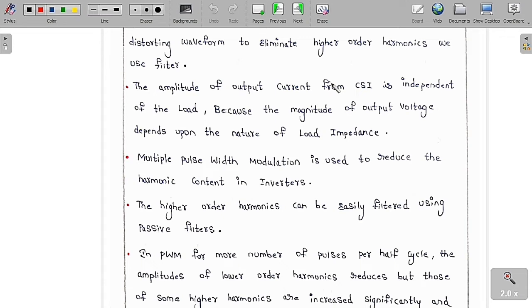So with the help of PWM switching, we can remove whatever harmonics we really want. But we prefer to remove the lower order harmonics because they distort the waveform in a much larger manner, as they have a huge peak value. So we try to remove the lower order harmonics by choosing the proper pulse width. As the higher order harmonics have a smaller peak value, we can easily remove them with the help of any filter. With this, THD decreases, as moderate filtering also happens.